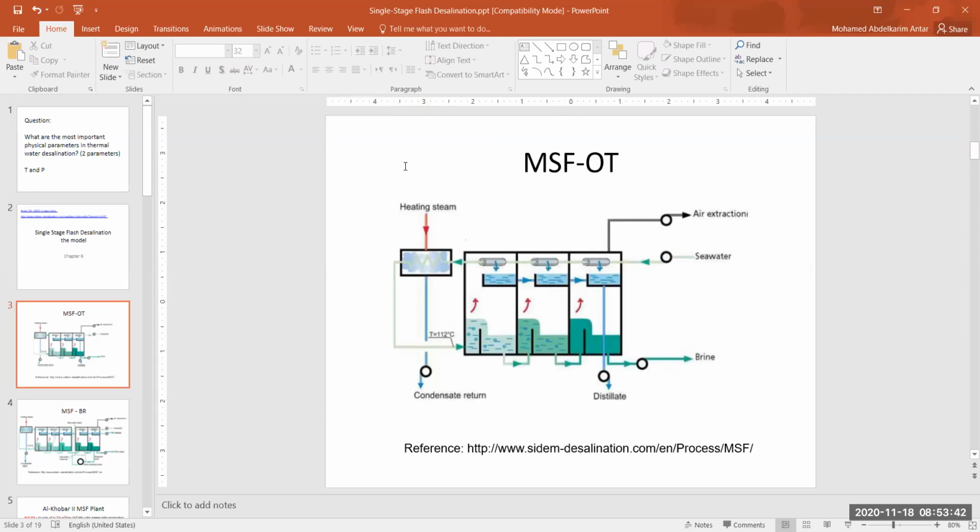The idea behind a thermal desalination multi-stage flash system, you can see it here. Seawater is entering into the tube bundle. The tube bundle is receiving seawater at normal seawater temperature, about 30 degrees centigrade or so. It is entering here, and the liquid here is being preheated. It is preheated by the vapor which is coming from below. So the vapor preheats the liquid. So we have preheating here, and preheating here.